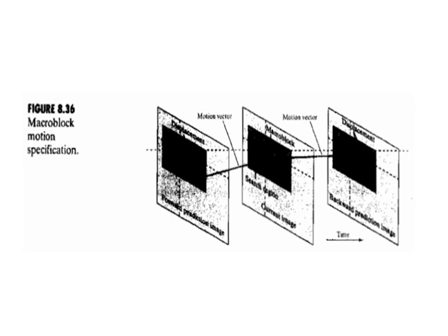An encoded frame that is based on the previous frame is called a predictive frame, that is P frame. One that is based on the subsequent frame is called a bidirectional frame, that is B frame. B frames require the compressed code stream to be reordered so that frames are presented to the decoder in the proper decoding sequence rather than the natural display order.